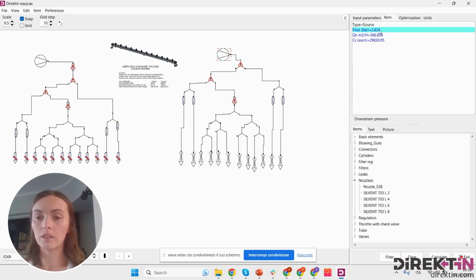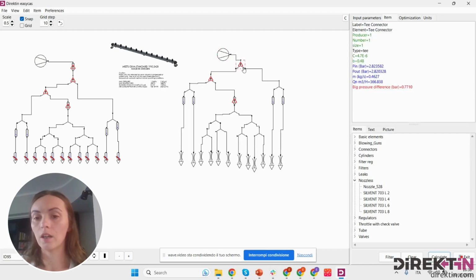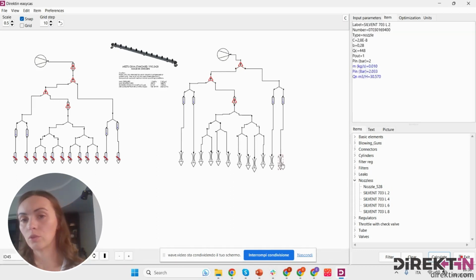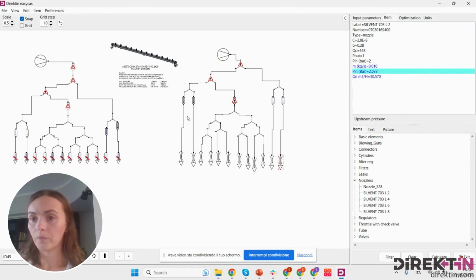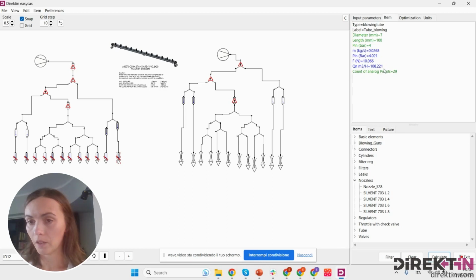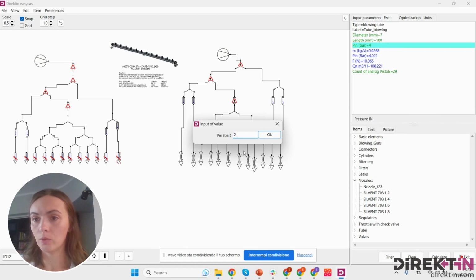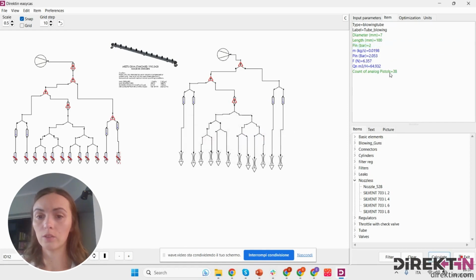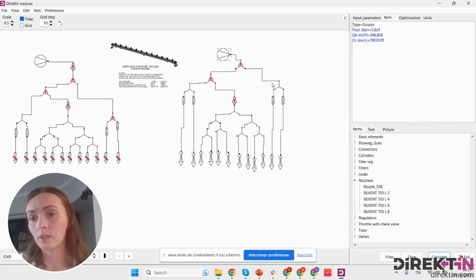So this is basically the real situation, that the pressure at the inlet of the machine was fluctuating, and around 3 bars, or 2 bar, was entering the machine. Then here on the outlet, we had around 2 bar, and this would correspond to the blowing force, not of 10 Newton, but let's recalculate the blowing force, because we can compare it with the open pipe, of 6.3 Newtons.